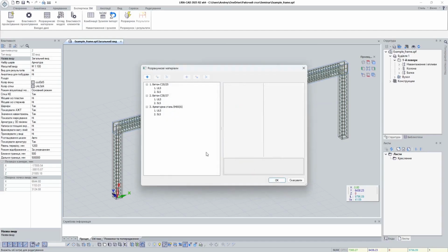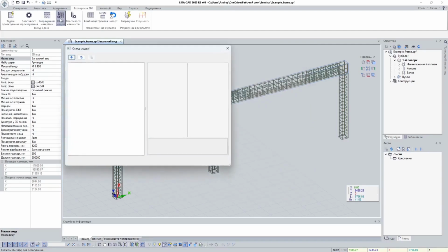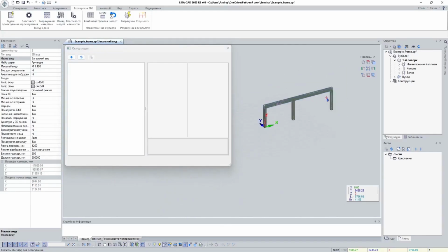It gives you a nice, clear, sort of hierarchical tree view of all your design objects and their properties within this system. Okay. To actually add elements from your main LIRA-CAD model, it's pretty straightforward. You just select the structures you want in the 3D view. Right. And click a button like Create Structural Elements from Selected. They then appear in the expertise system's model. And then you link them up.